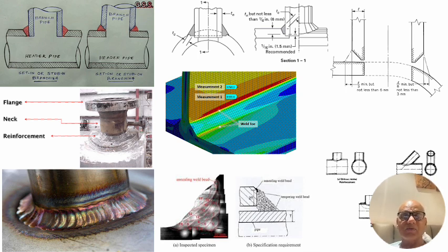That is where the crack will initiate, and the weld will remain intact, but the parent metal will crack, and then we'll start blaming the parent metal, or saying there may be an inherent defect. "My welding is good." That may be a possibility. I'm not saying that the parent metal may not be bad, but since we know that there is going to be a stress concentration, and the placement and the distortion, it is the welder's duty to really see that while he is welding, it doesn't distort, it doesn't give more stresses onto the top of this weld.